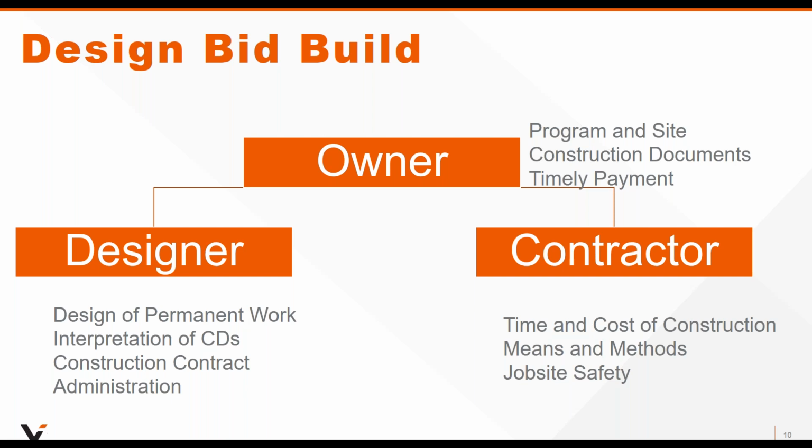Now, here's an important concept that oftentimes comes into play in a design bid build environment that doesn't play an important role in design build. It's called the Spearin Doctrine. And this is a legal doctrine that when the owner gives the contractor a set of construction documents, they are giving them an implied warranty that there's enough information in these documents for the contractor to bid and price and complete the project, and that the contractor is entitled to rely on it.